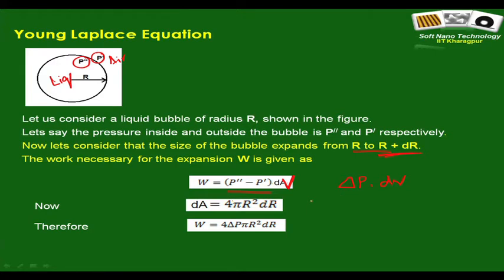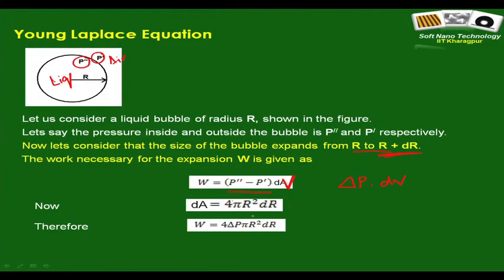We have a tendency, when we draw a piston, of considering the work to be P dV. We consider it to be P because we simply assume that the other side is open to atmospheric pressure. So, if we consider the gauge pressure, it is only P.